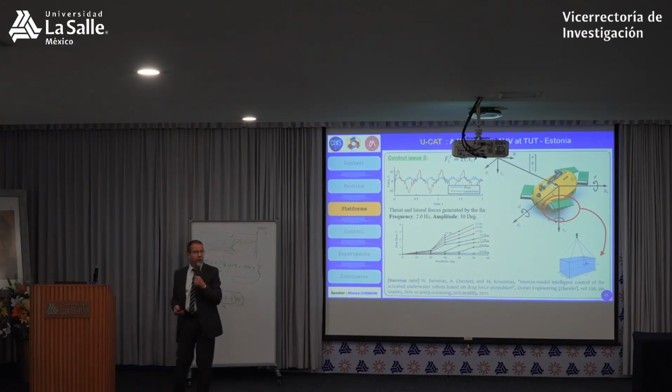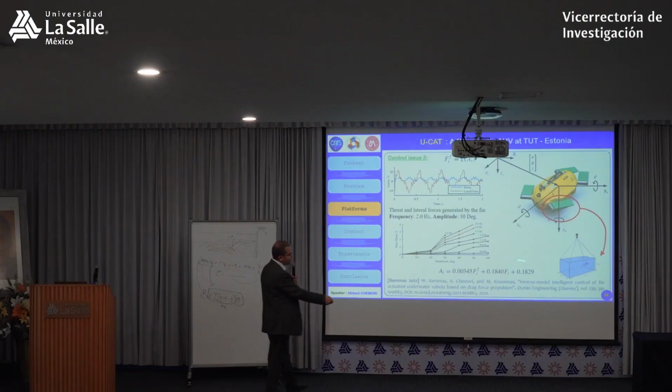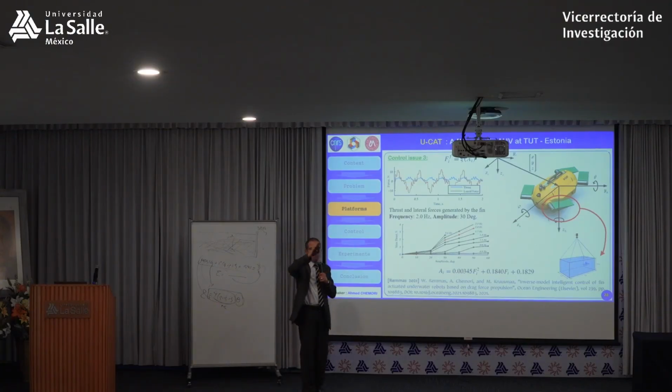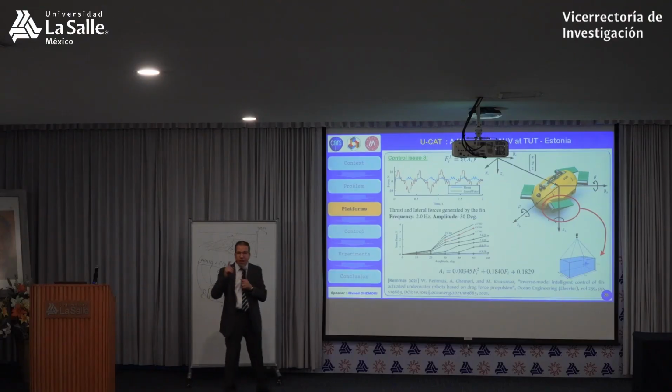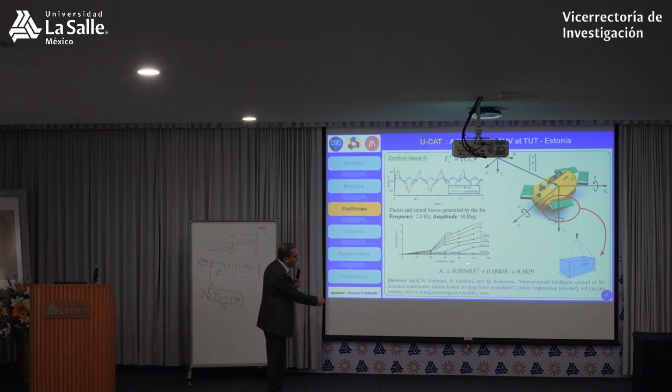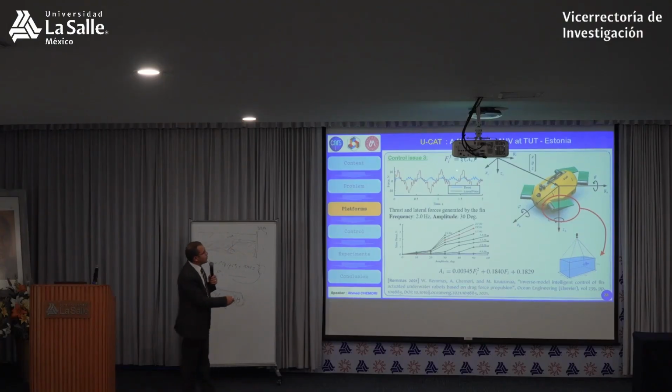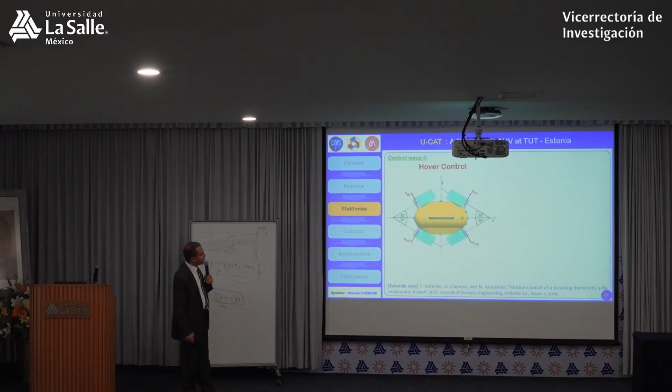And in terms of model, we try to find a compromise, a simplified model. It's not a big complex one, it's a simple one. We invert this model, and here you have the amplitude in terms of thrust. So it means if I want a specific thrust, 10, you replace it in the model and you obtain the amplitude that will give you the thrust of 10, you understand? And so on. And we use this. This is a control issue.